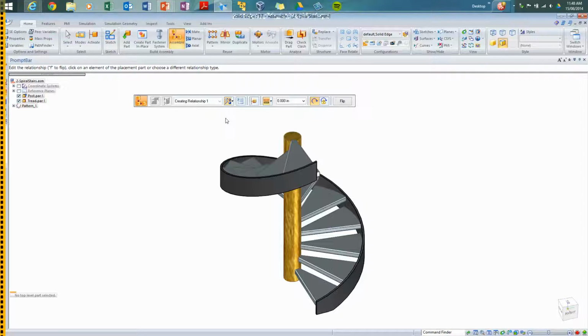The ground relationship, you can now fence select or shift select multiple elements. If you need to ground loaded components, you can do it in one go rather than have to select a component, click on the ground command, select a component, click on the ground command, etc.